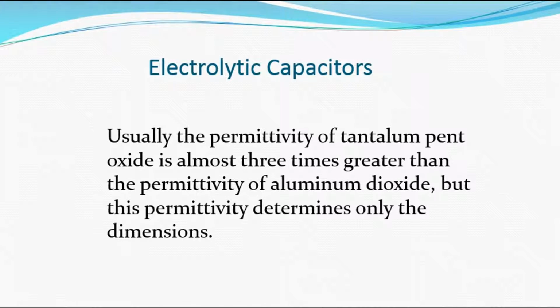So in that case, for an electrolytic capacitor, the permittivity of tantalum pentoxide is almost 3 times greater than the permittivity of aluminum oxide. But this permittivity determines only the dimensions. The work of permittivity in a capacitor is only to determine its dimensions, its size.